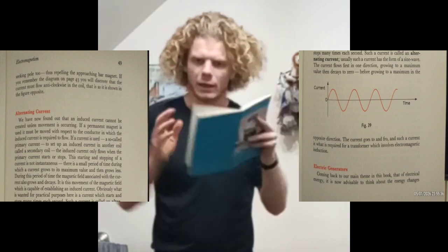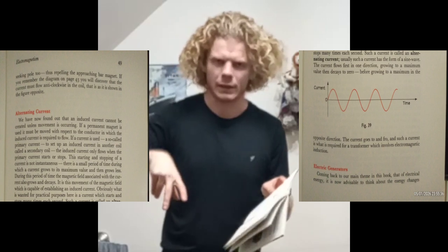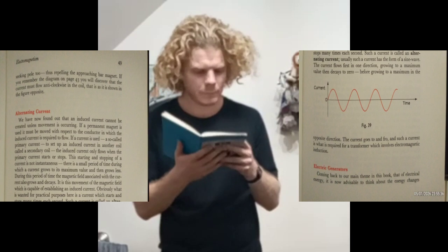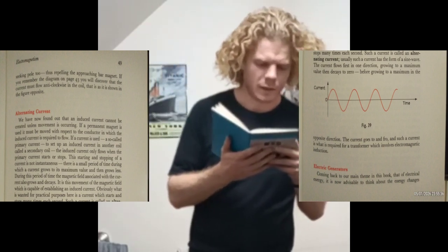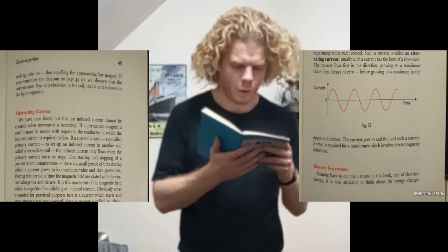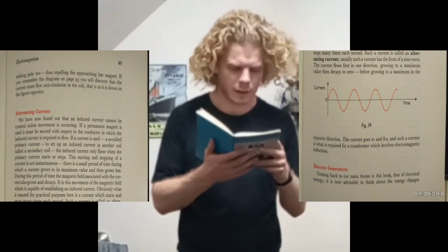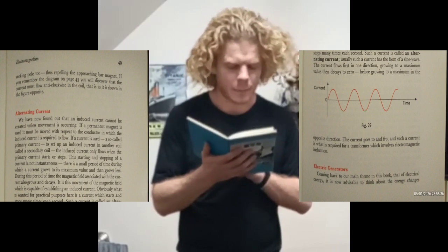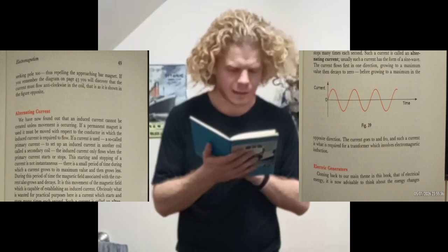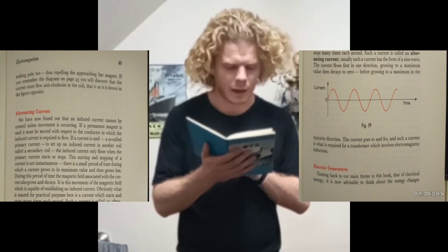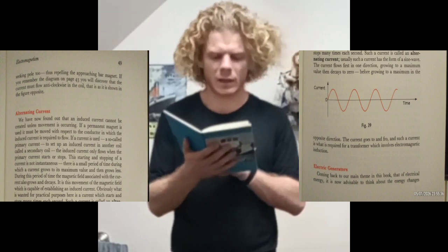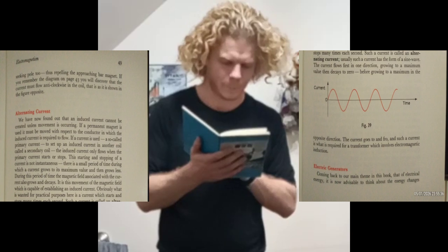Okay, the thing with the bending, and when we're having the output of a magnetic field at both ends together, then you can use both. That is all the lines of force traveling either the core or the piece of material being lifted. You should note that the closed circuit is a magnet insofar as magnetic lines of force exist in it, but there are really no free poles, as at no end do the lines of force leave the magnetic material to pass into the air.